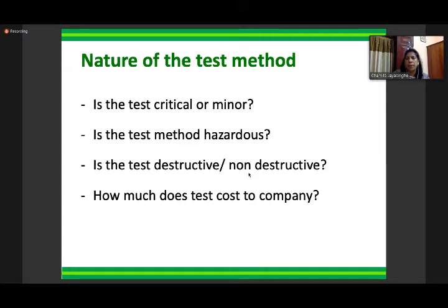Yes. If it is a liquid, we can also do it, because we can trap it. We can use a beaker or whatever container. First we take the measurement of the container, after that we put the liquid in, then get the difference of the weight. So to determine the weight, that is okay. But sometimes the weights differ, maybe 5 grams, 1 gram, 0.5 gram, 0.1 gram, or 100 grams, 1 kilo. In such a situation, you have to change the analytical balance, but not the test method. So the weighing gravimetry method is okay, universal.